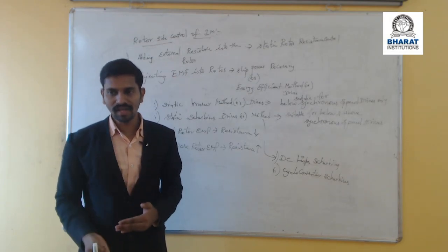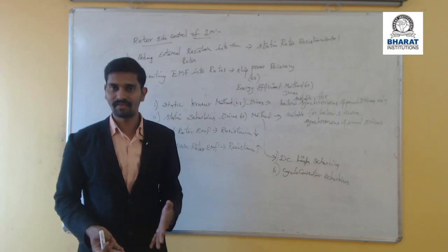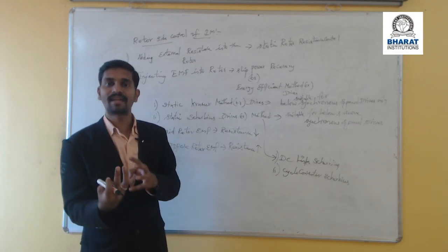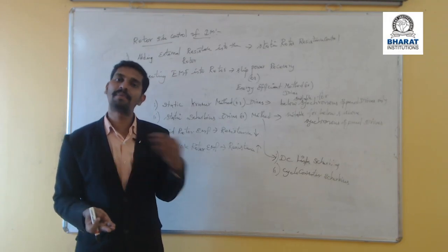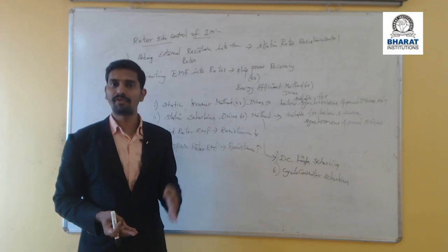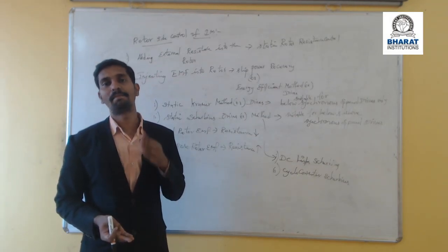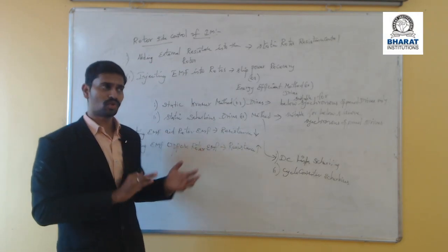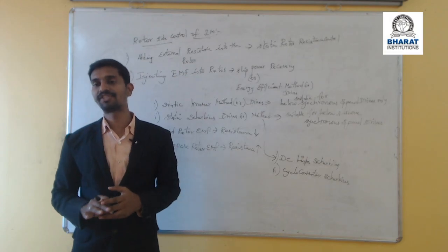To overcome that limitation, the next method, slip power recovery, is proposed. We recover the slip power and use it for motor power provision or feed it back to the supply system. So the motor performs in a highly efficient manner and the losses are minimized. This is about the rotor side control methodology of the induction motor.